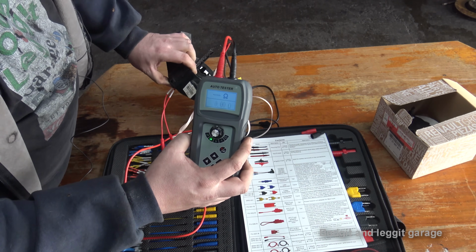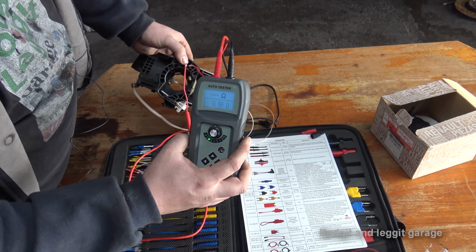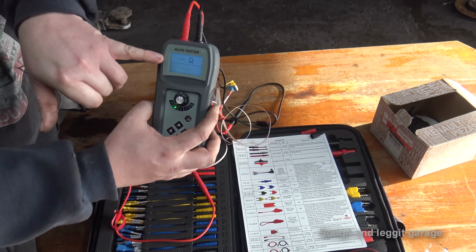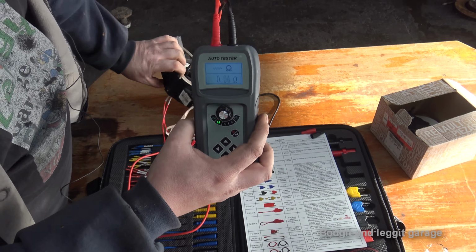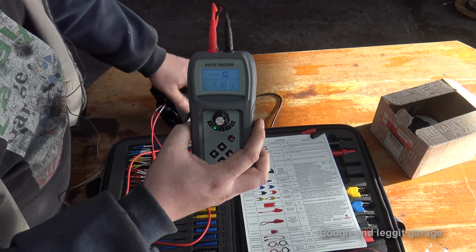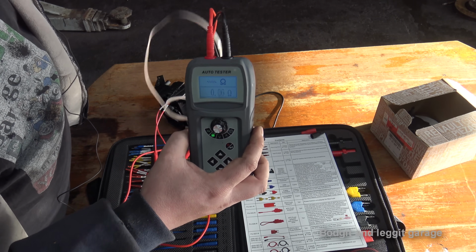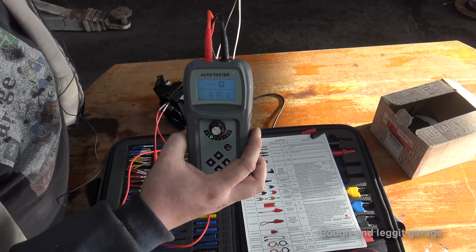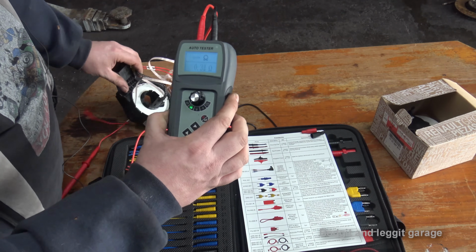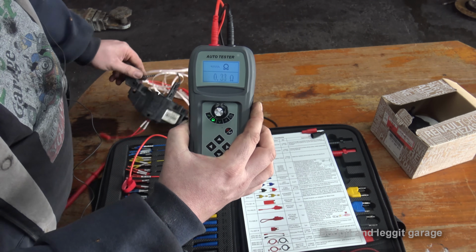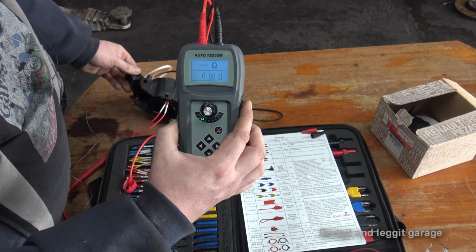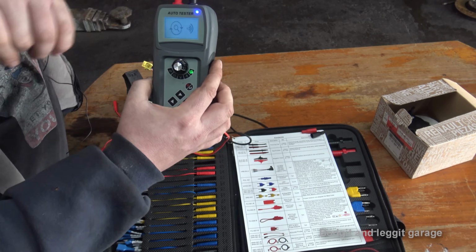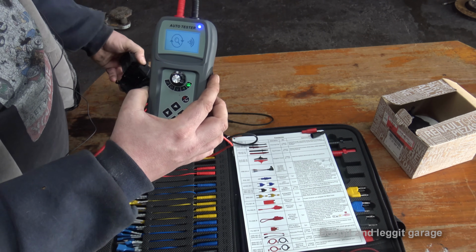Oh, see if we can get something. No, it's just all over the shop. I can't even get a proper reading. So this is where an ohms test comes in a lot better than, there we go, we've got a reading there, but as I move the cable, it's just going all over the place. So there you can see on the bad one, it is just all over the place. That should be a nice steady reading, and it's just all over the place. That's where a continuity test can get you stuck.